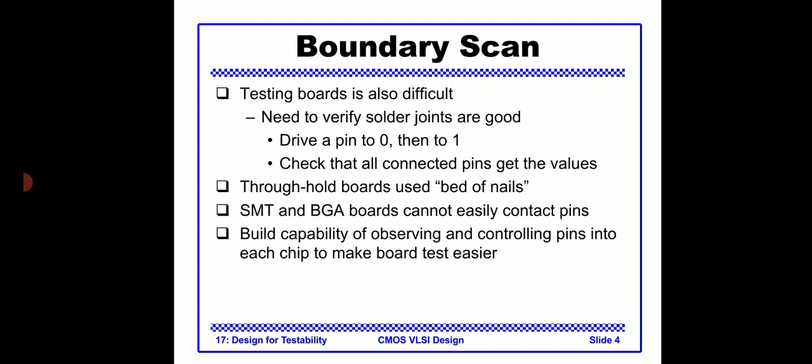This significantly reduces the cost of automatic test pattern generation. Also, the main thing is that it reduces the storage and maintenance of test patterns. It can test many units in parallel, takes shorter test application times, and functional speed is very high. Boundary scan provides a means to test interconnects and clusters of logic.